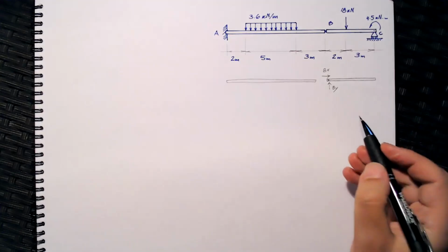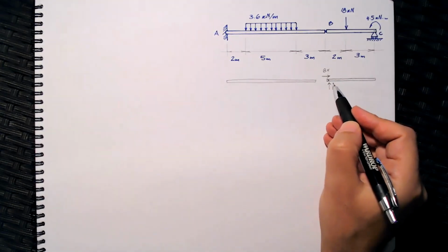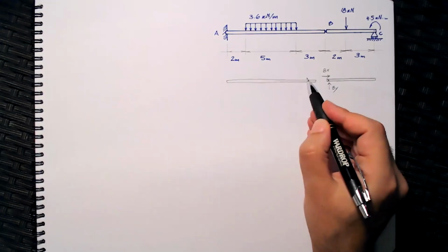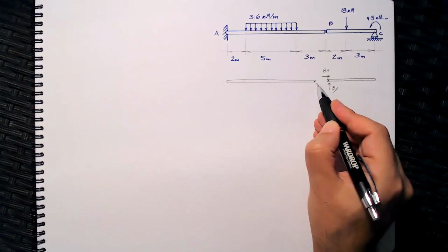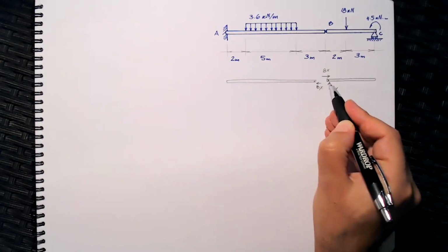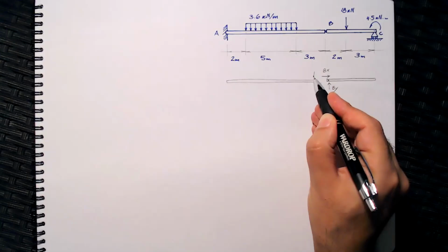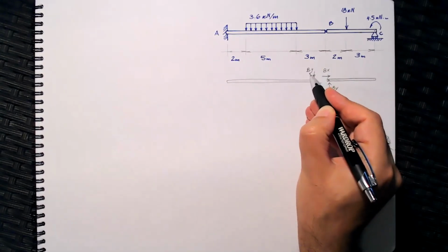So that's the rule. It says deal with it as if it's a hinge support, but very quickly take the same magnitude but opposite direction and flip it on the opposite side of the structure. So you take this force, the same magnitude, Bx, and if you assume it's going upward, you assume it going downward here, and you call it the same name, By.